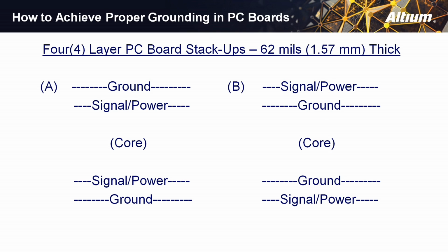And now all of the signals referenced ground, so when we changed layers, we didn't have to worry about trying to move energy across a large dielectric space that was going to cause interference. We lowered the EMI signature of that board by 12 or 14 dB. It was a major improvement.